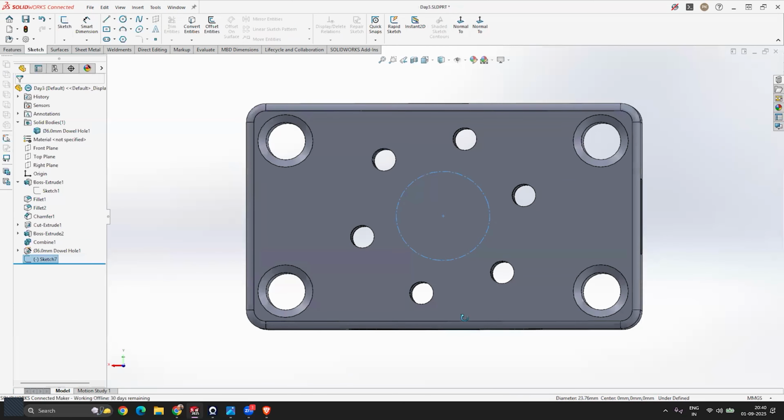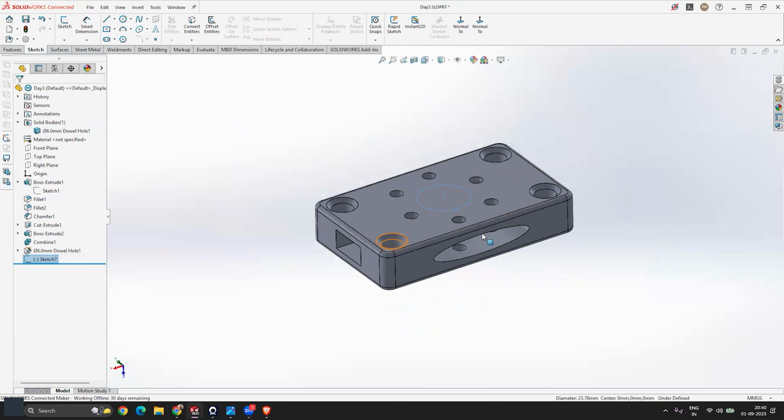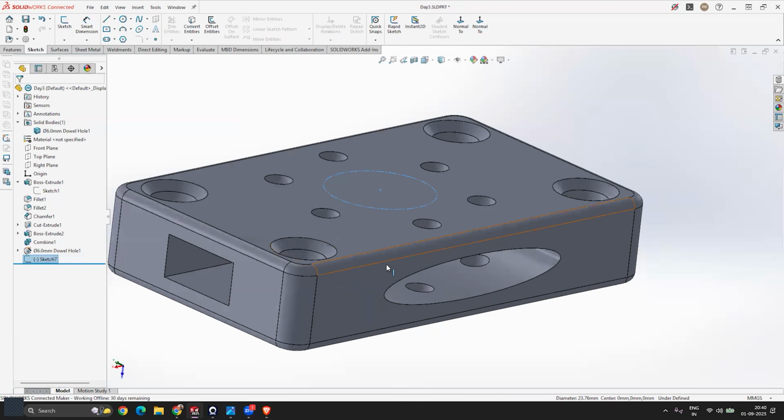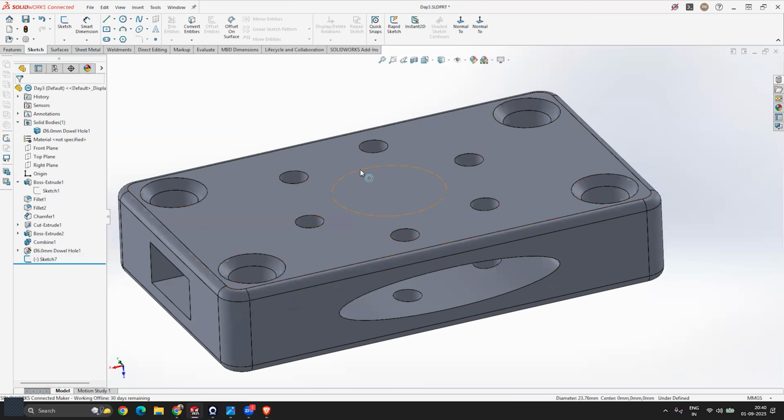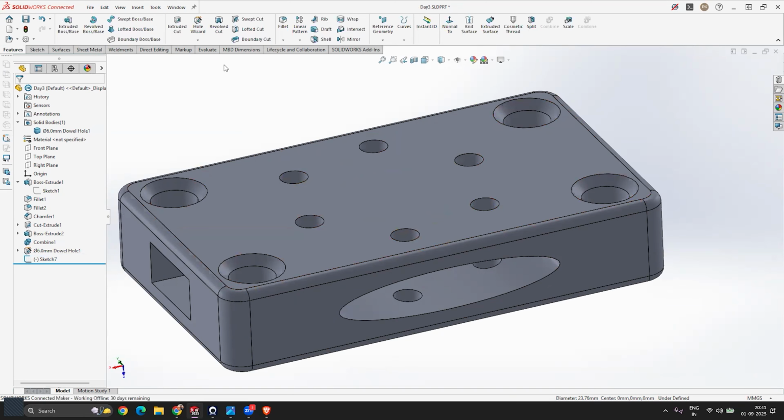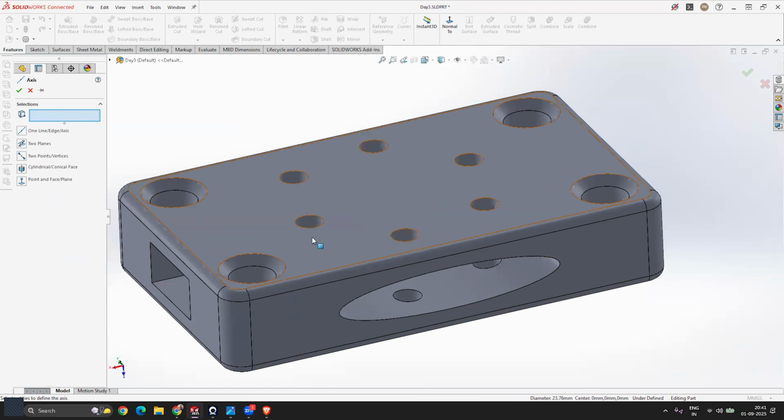Click on finish. Wherever we are repeating something, I am doing it quickly so we can save some time, right? Here you can see what we did: we have created a circle onto this flat face. Now we'll go back to the feature panel, tool panel, and activate this tool that says axis, and then select this circle.